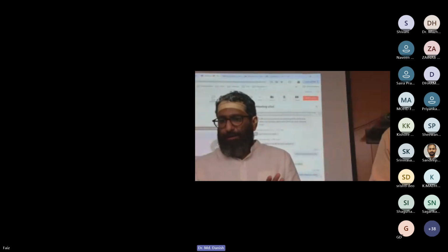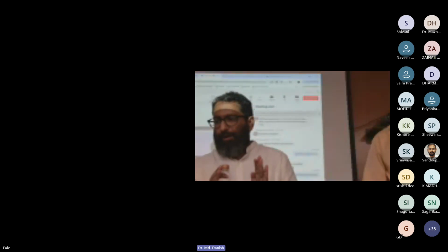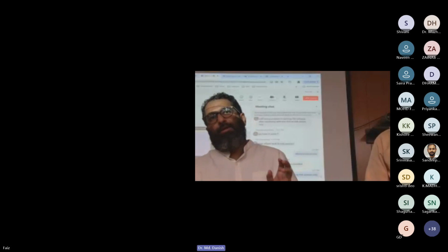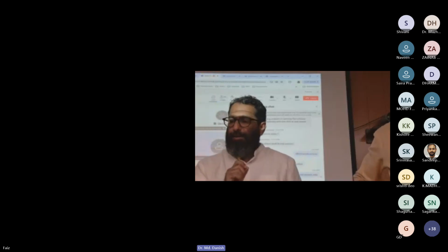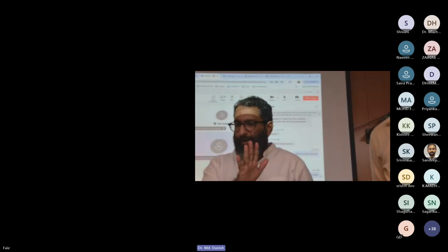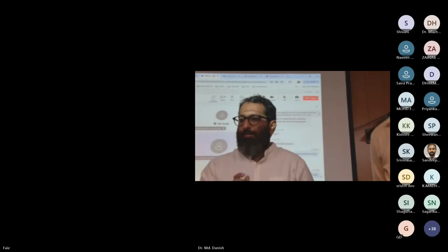In the trial version, there is a limitation of size. We can model up to 50 grid in X, 50 grid in Y, and 25 to 40 grid in Z. So all the analysis will be restricted to that. It all depends on how we conceptualize. I'll explain in the afternoon. For example, let's say you have a 500 meter by 500 meter area, but in the software we have only 50 by 50.